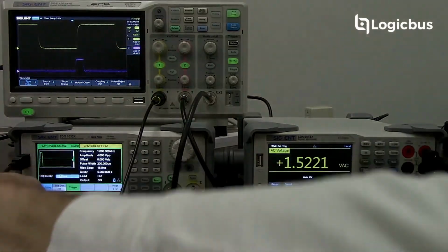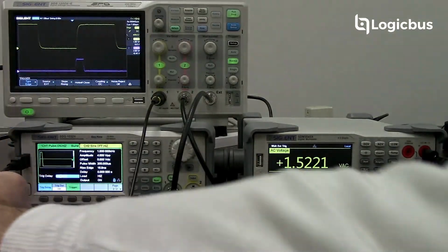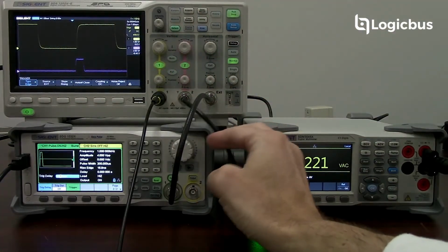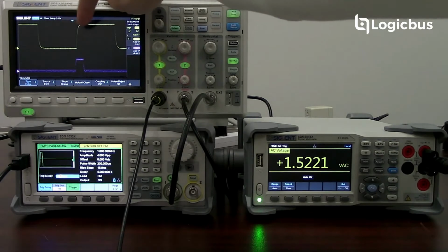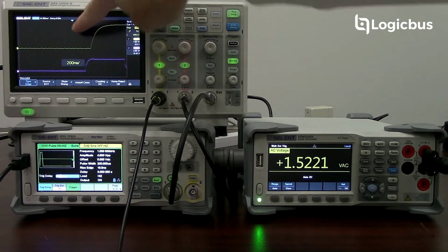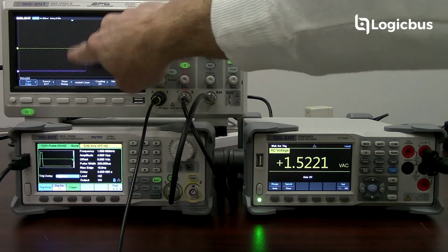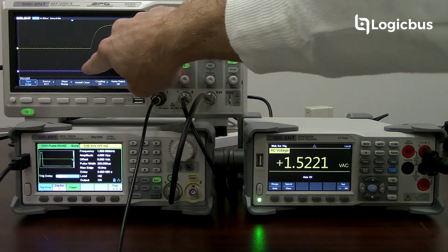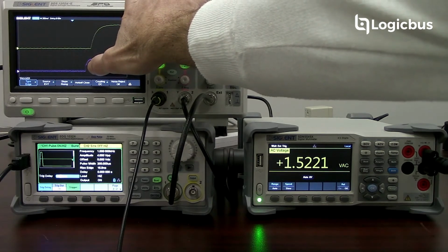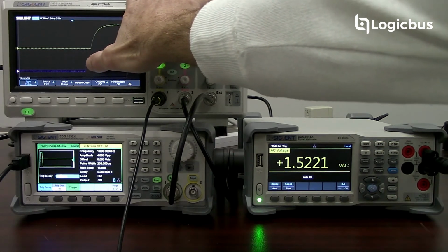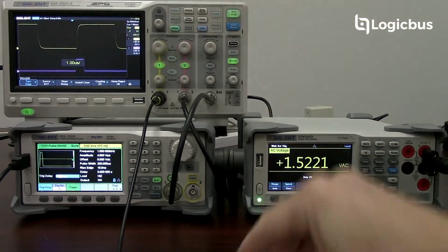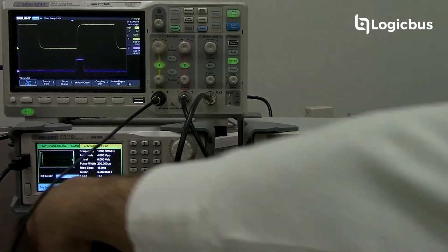So the yellow trace is channel 1. You'll see when I have a square wave, that's coming off of a demo board that I have here. And then we're measuring the actual trigger output from the back of the oscilloscope. You can get an idea of some of the delay here. So here is our trigger point, and we're at 200 nanoseconds per division, so that's 200 nanoseconds. So we're at about 350, maybe 375 nanoseconds of delay. So that is something that you're going to want to keep in mind when you're making those measurements.